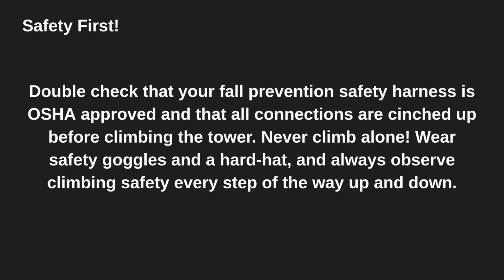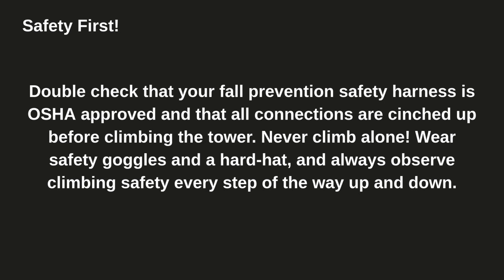Now, if you're going to climb on your tower, if you happen to have a tower, we have a 40-foot tower in our backyard, even though people somehow manage to not see it, but we do have one back there. Double check that your fall prevention safety harness is OSHA approved and that all connections are cinched up before climbing the tower. Never climb alone. Wear safety goggles and a hard hat, and always observe climbing safety every step of the way, up and down.